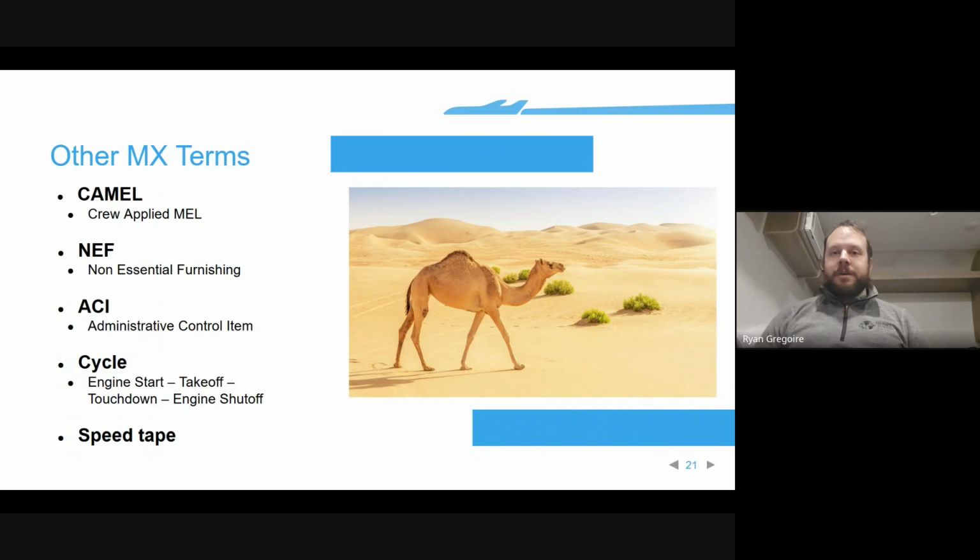You'll probably hear, oh, we'll just put some speed tape over it and we'll be good to go. What they're doing is usually that's some part of the aircraft where there is no longer a smooth aerodynamic flow. They're putting speed tape over it to restore a smoother aerodynamic flow and then continuing, or they're doing it to protect an area from disturbance from the air. It's not a structural tape. It is simply there to ensure that air flows a specific way.